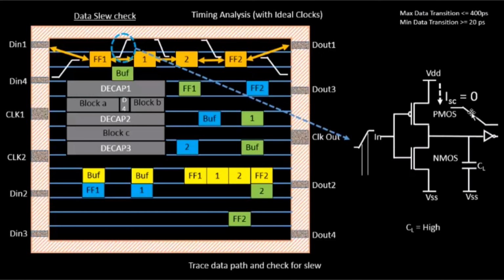So for this particular logic, because of this huge transition, you see a huge amount of short circuit current for this particular inverter. Okay, so output load capacitance should be again within certain limits, and one way to measure the output load capacitance is to measure the transition value. So if the output transition at this point, or let's say the transition of this particular waveform is less than 400 picosecond, we are in certain limits. Okay, this is a very good technique to reduce the short circuit power, but it should not be used very extensively because of reasons that the next stage will get affected.